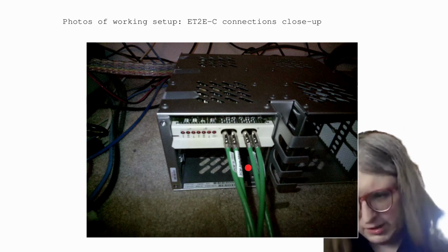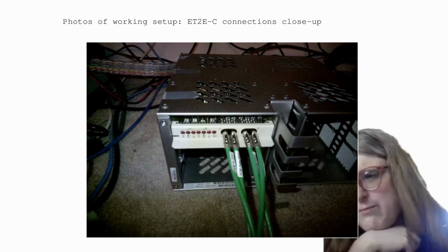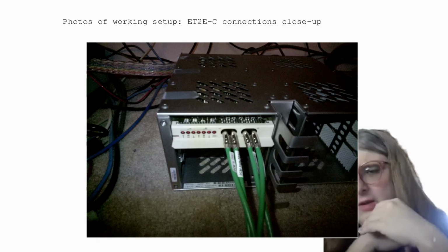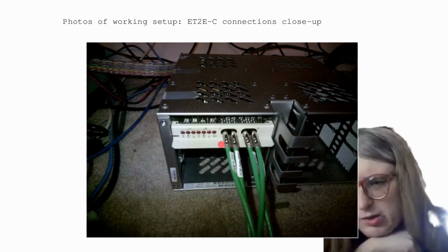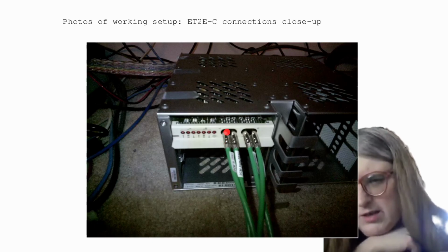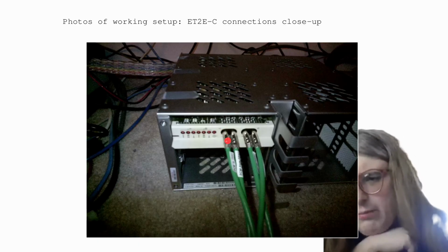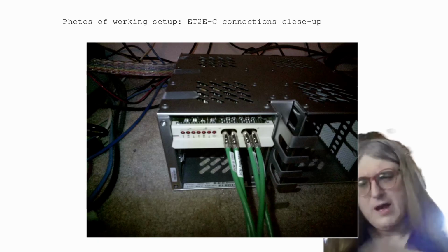And these are the cables that go in. You can see why I had to get special cables. I couldn't just get any random coaxial cable with the mini BNC plug, because the most common types of mini BNC plugs have a bulky piece. The mating end of the mini SMB plug is standardized, otherwise it wouldn't be mini SMB. But the most common plugs also have a bulky piece in the back, which is not part of the mating interface.